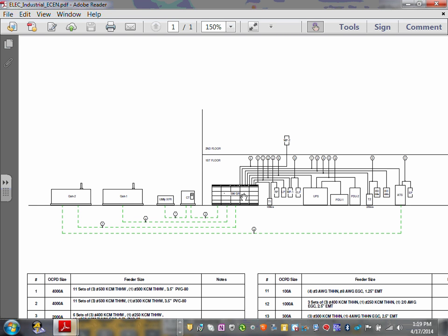Now, if you have a small shop, you can put all your receptacles and all your mechanical equipment and all your lights in one big 600 amp panel and distribute it right there, right? Does that make sense? So it's small, 600, done. A lot of you guys do that all the time. No sub panels whatsoever. So that's okay.